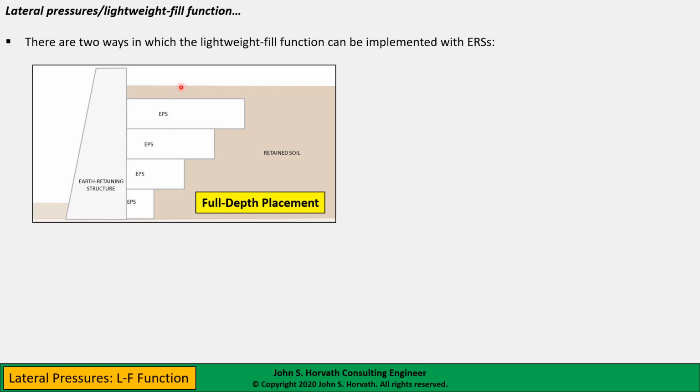We do have to leave a few feet, a meter or so at least, at the top. And this is typically because we have a pavement system up here, so we need to be concerned about stresses from whatever vehicle is using that pavement on the EPS. Need to worry about differential icing where appropriate in the climate, as I mentioned previously.